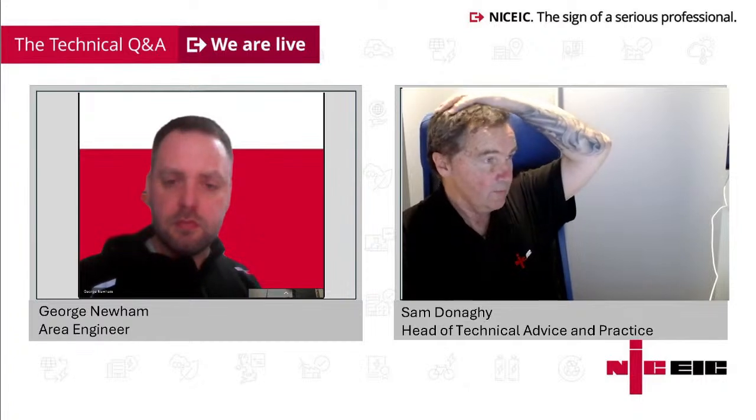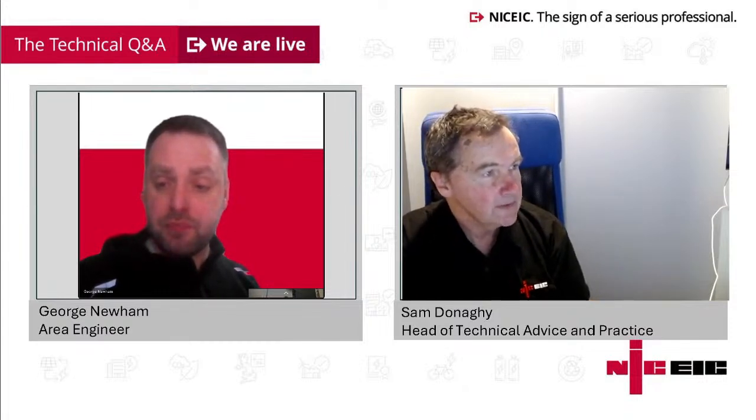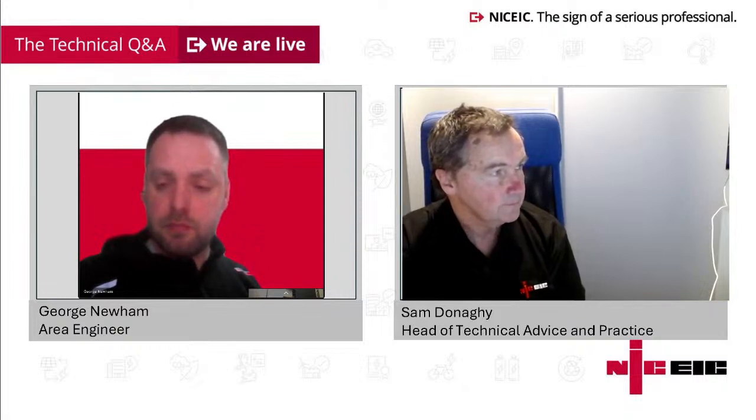Yeah, might need to just, so yeah, nothing there that says, obviously 3-phase 40 amp supply. If it's hardwired, depending upon how you run the cable, you may not need RCD protection. It's obviously not going to be fed from socket outlets. So yeah, just need a little bit more information in that one.